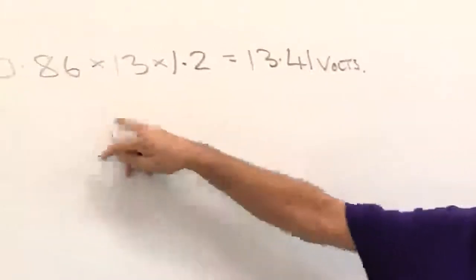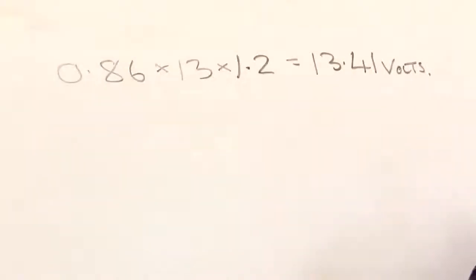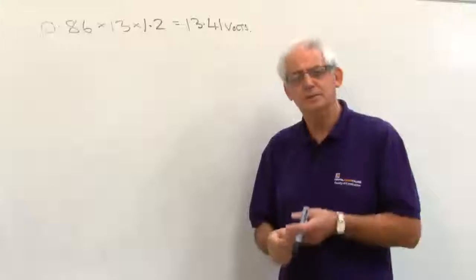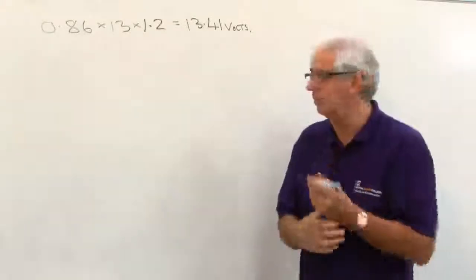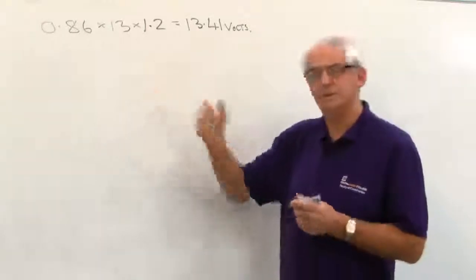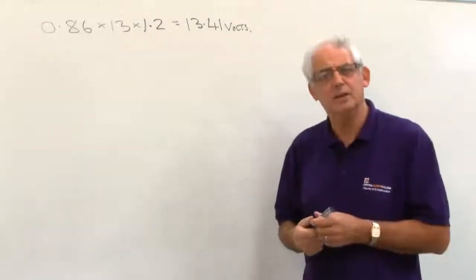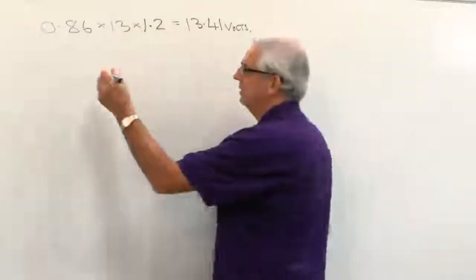But again, we also know that this R1 and R2 value is made up of a 2.5 line conductor and a 1.5 CPC. So using the process we used before, we can calculate the resistance of our line conductor only. Simple process.